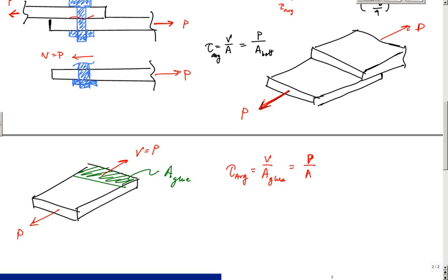This is the basic idea behind bolted connections in steel construction, and something you might find in ASME or AISC codes. And the formulas are basically the same. There's this idea of tau average equal to V over A, except there's some code modifications depending on the surface or the materials that are used, and other ways besides just failing in the bolt. There's other ways that a connection can fail, but we're not going to address that here.